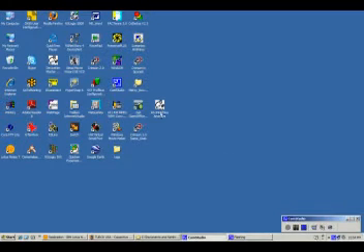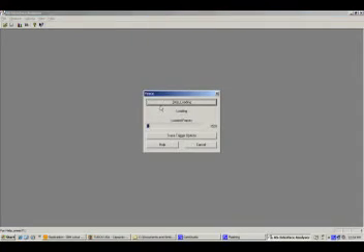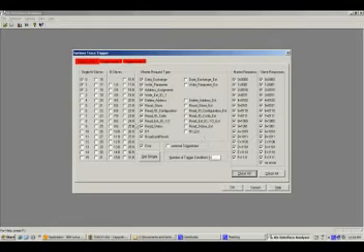Okay, now we're going to go ahead and open up the ASI Interface Analyzer software. And you'll see that once I open that, it actually is starting to load traces of the messages happening on this network. And you can do all kinds of things, such as hit the trace trigger options right here and go on the page and decipher what particular nodes that you want to monitor data from and so forth, and what kind of master and slave responses and packets that you wish to log.